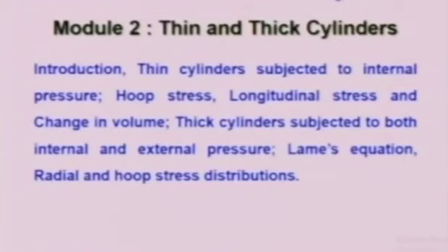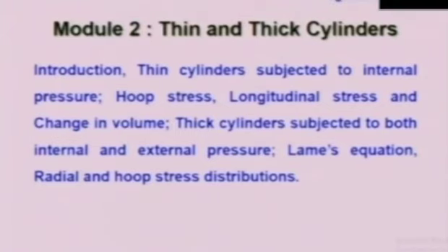Now, coming to some of the contents of this particular program, which comes under module 2R: the introduction, then thin and thick cylinders, basically thin cylinders subjected to internal pressures, what we understand by hoop stress, longitudinal stress and change in volume on thin cylinders. We also talk about thick cylinders subjected to both internal and external pressures. And finally, the most important equations in thick cylinders, that is Lamè's equations, which tell us about the way in which the radial stress and hoop stresses are distributed over the wall of a thick cylinder.